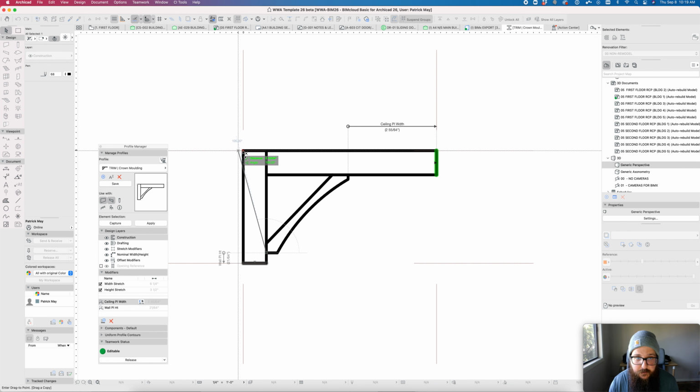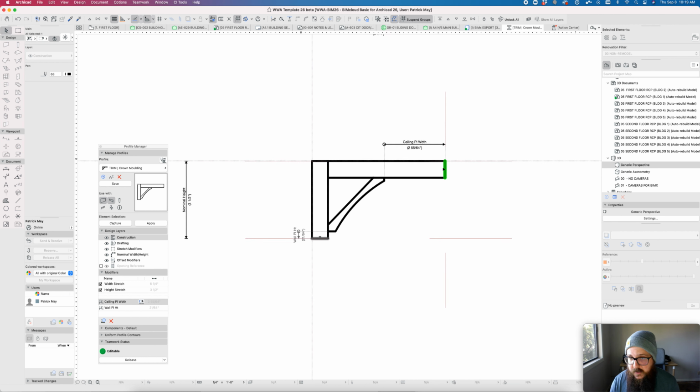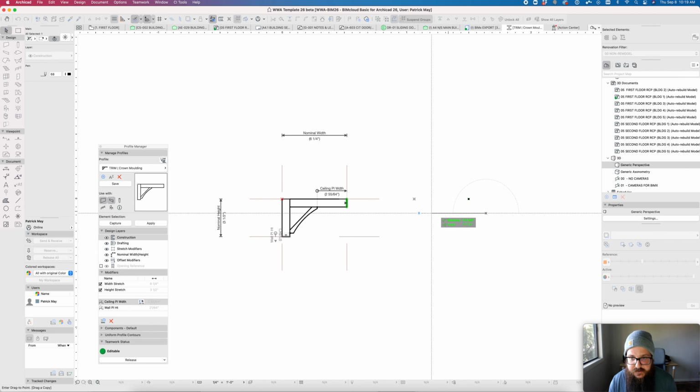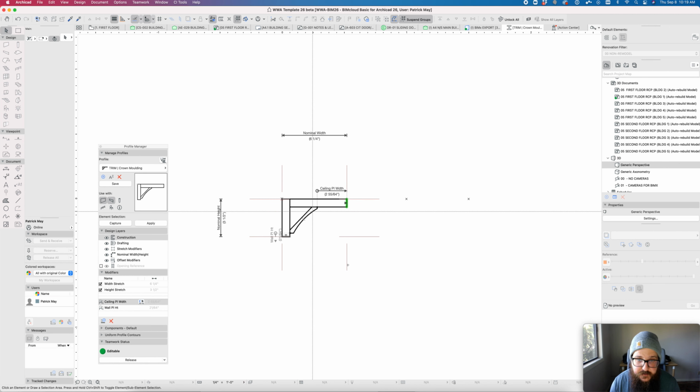Or I can have a snap point, like I said, if I needed the ceiling to have an option of, let's say, 1.5 feet thickness, putting a hotspot out here at 1.5 feet is going to give me the ability to stretch that to that point really quickly without having to figure out what that extra width is going to need to be. So if it's like option A, option B, option C, I could even pull this back 6 inches and give multiple options there.